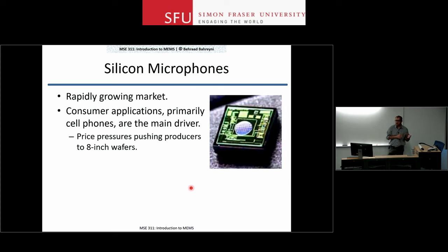So in case of microphones, because the acoustic pressure is usually much, much weaker than what you expect in, let's say, DC pressure measurements, capacitive sensing is good enough. We don't really need piezoresistive sensing. You're measuring micropascals or millipascals at most, but it's usually on the order of micropascals of pressure change, versus a pressure sensor may measure tens or thousands or even tens of thousands of pascals in pressure variations.